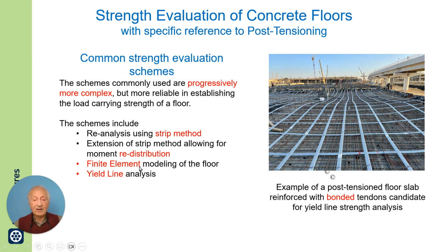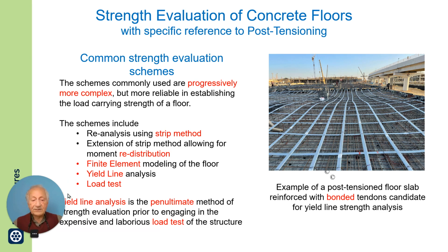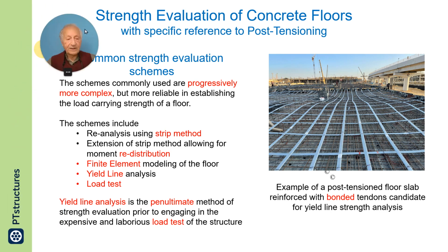Finite element is based on the elastic solution. Now I take the opportunity to mention that the yield line is post-elastic. And if yield line doesn't work, the ultimate is load test. Yield line analysis is the penultimate method of strength evaluation prior to engaging in the expensive and more complex, laborious load test.